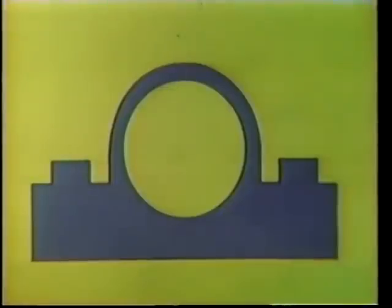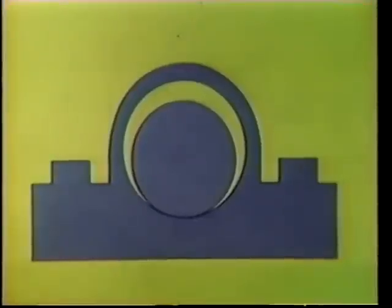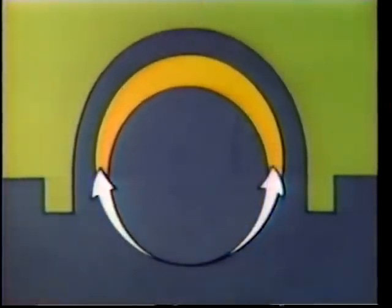Now let's take a look at how this works in a plain journal bearing. A plain journal bearing consists of a bearing sleeve which surrounds a shaft. The space between the bearing and the shaft is filled with lubricating oil. When the shaft is at rest, most of the oil is squeezed out from between the shaft and the bearing by the weight of the shaft.